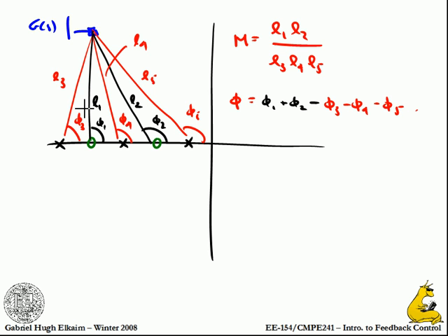And notice, of course, that now I've got a root locus. I can tell you where the roots are going as a function of my gain. And if I know where my roots are going as a function of my gain, and I know where the acceptable regions within my complex plane are, I've got design here. I can actually say, hey, I know exactly what I need to do to make my system hit the specs that I need.